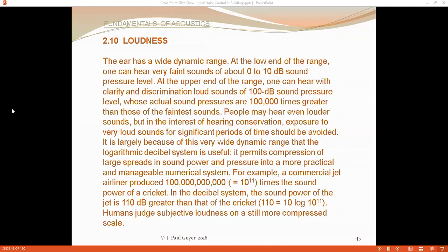And so you write all of these readings down, and you then, using the ASTM methodology that is recommended, blend them together by averaging them or taking the median or something like that. And what you end up with is a single number in units of decibels, which represents the sound being produced in the source room.